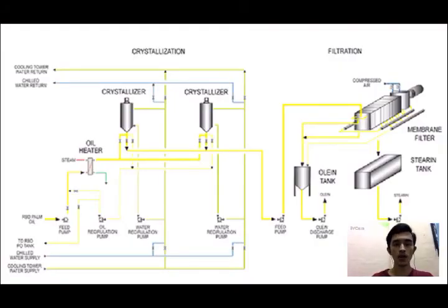In the process of oil, a fractionation process consists of a controlled cooling of the oil, thereby inducing a partial or fractional crystallization. The remaining liquid oil is then separated from the solid fraction by means of filtration or centrifugation.